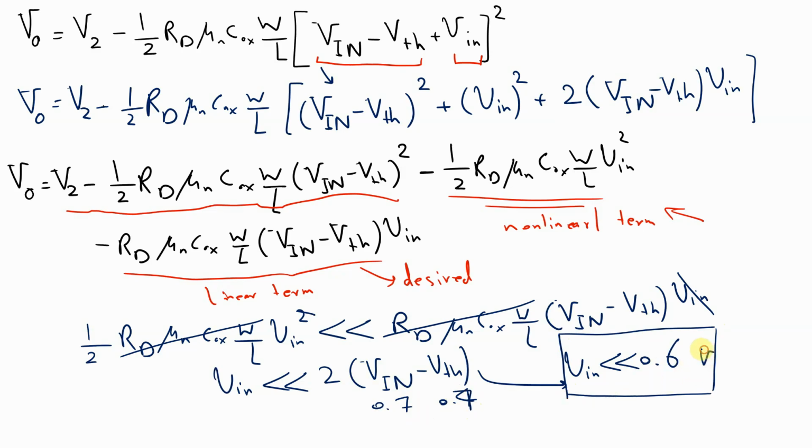about 600 millivolt. Okay, and I chose 30 millivolt in my previous video for this amplifier. So this is a small signal condition, and this is how we can calculate it. Complete process. And now I'm going to look at the distortion, how we can come up with a formula for distortion, and after that we're going to check both of these formulas in our LTspice to clarify our results.